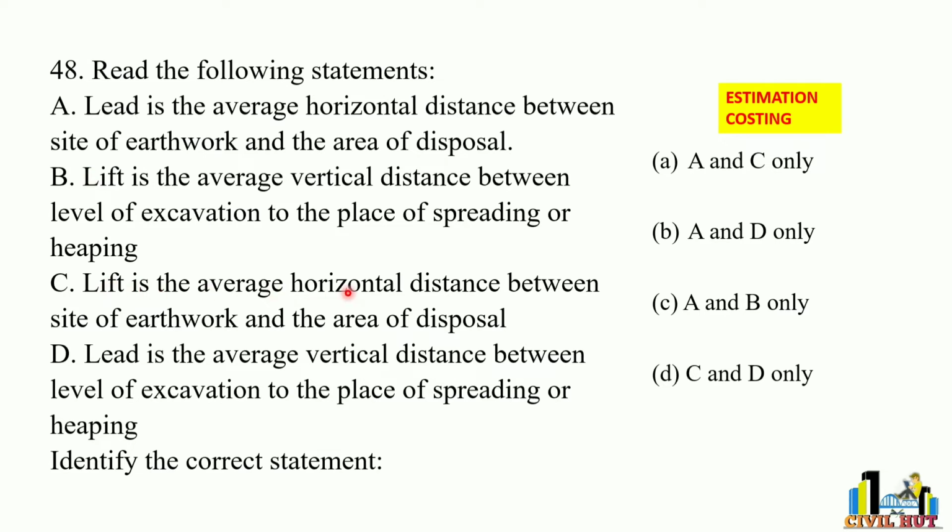Lift is the average horizontal distance. No, lift is not a horizontal distance, it is the vertical height. Lead is the average vertical distance. No, lead is the horizontal distance. So remember this: lead is the average horizontal distance, lift is the average vertical distance.